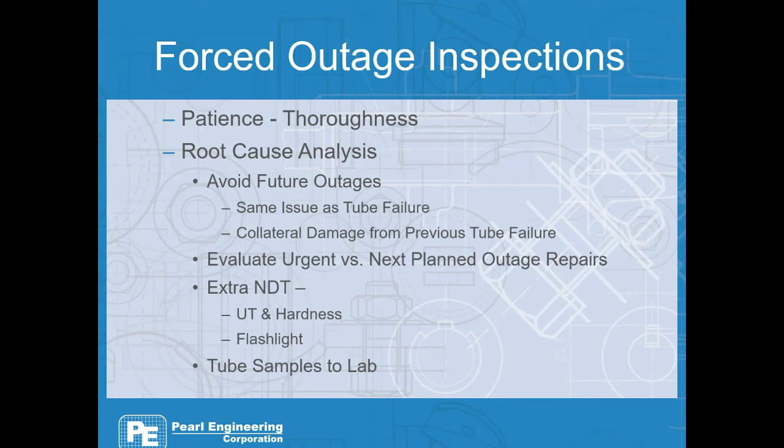If you can, collect a tube sample from the failure. If you're not sure why it happened, you can have metallographs done on the tube. You can have experts look at the failure and try to figure out why it happened.